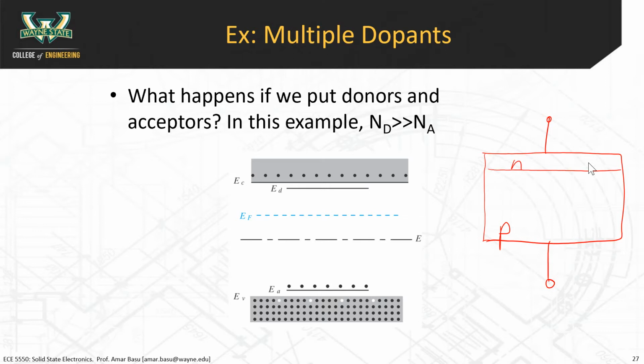Because you can't just take an n-type and a p-type material, put it together, and expect to make a good quality diode, because the interfaces between the two materials are not atomically smooth. It's better to actually diffuse in the dopants.